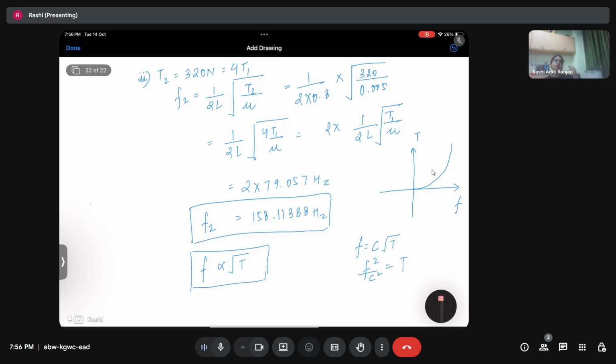But in those softwares also, we use meshing techniques. So every 3D model is made into small parts, and those small parts are then solved using numerical techniques for the partial differential equation. The smaller the part gets, the more the accuracy is, but the more is the computational cost. So there is always an optimization between the computational cost or time of computation and the accuracy that we want for our system.